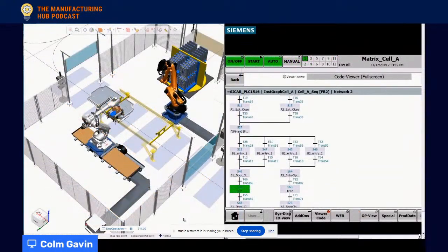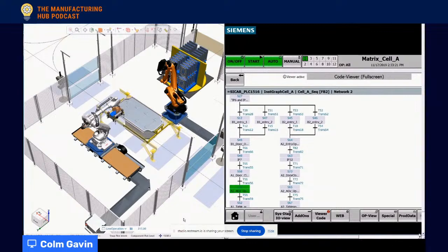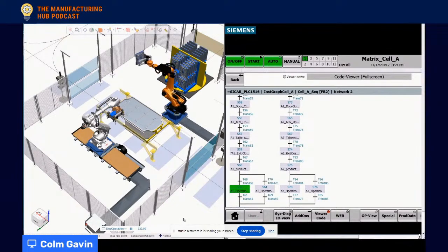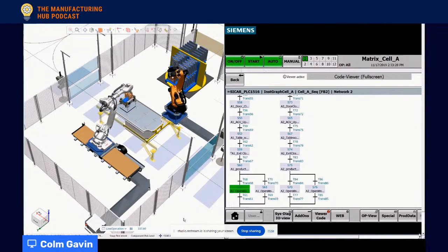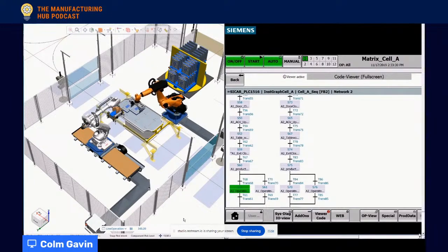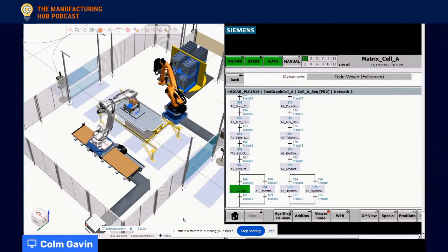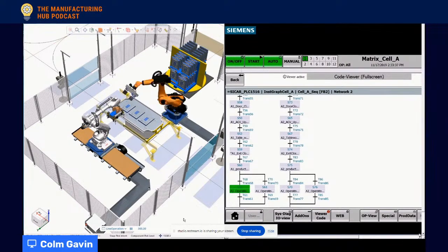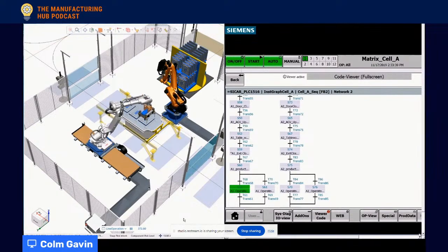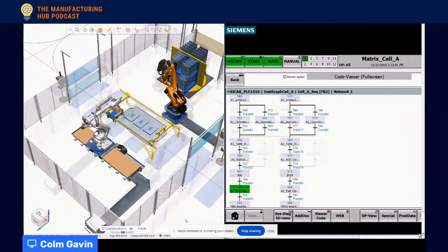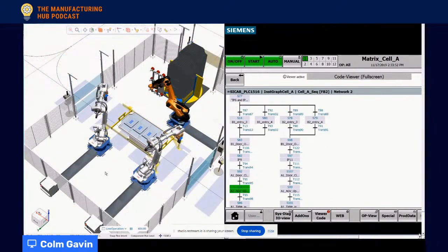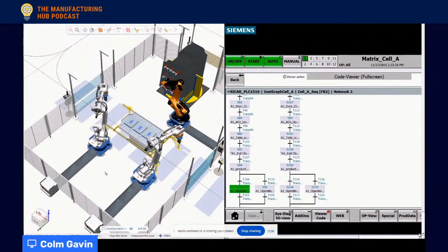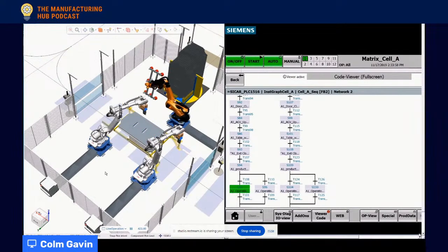So what you see here on the left-hand side is a simulation software for programming the robots, and that's robot agnostic. So KUKA, FANUC, ABB, whatever, with our process simulate software, we can bring those part files in from those vendors into the software. And then we can teach the path, the robot trajectory, the end of arm reach, making sure we're not going to crash into anything. But of course, in this robotic cell, as you can imagine, the AGVs or conveyors or guarding system, that's all controlled by a PLC.